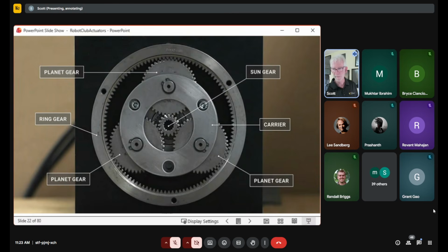They have a little bit of backlash in there, but overall they have fairly good properties, but a lot of it will come down to volumetric density and how much room you have, because when we're building a humanoid, a lot of times we're concerned with the overall size of our actuator, and sometimes the planetary gear might be too big. However, it's pretty popular, and as we'll see, everyone sort of shifted away from it, and now we're taking a second look at it. So even though it's the oldest and there are other replacements, everyone's coming back to it.